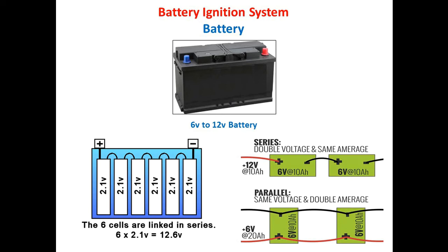Lead acid batteries are used for light duty engine applications, and alkaline batteries are utilized for heavy duty engine applications. Talking about lead acid batteries, these are formed by a number of cells of potential 2 volts. Number of cells can be connected together in series or in parallel. For a 12 volt battery, we have to connect 6 cells of 2 volts.